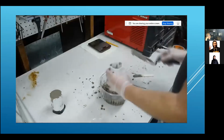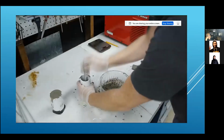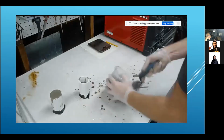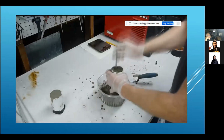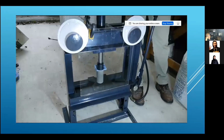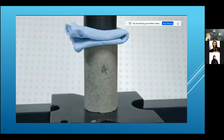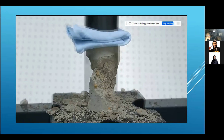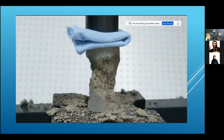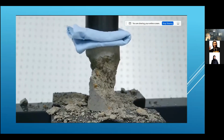Here's a demonstration. These two concrete cylinders were cast from the exact same batch, and we'll see just how much load they can withstand before failure. First, the compressive test. Under compression, the cylinder broke at a load of about 1,000 pounds. That's 450 kilos. For concrete, that's pretty low because I included a lot of water in this mix.